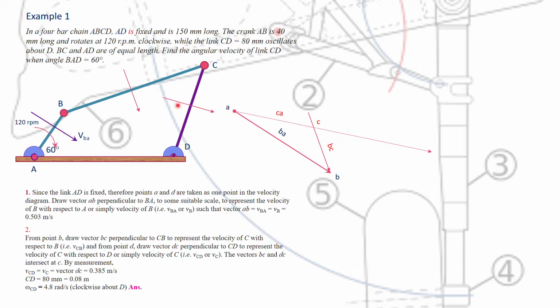Now BC, that is this. Once you have drawn it, the arrow should be pointing downwards. So you just put it downwards, and then you put B relative to C because your arrow is pointing towards B. You can put your arrow pointing towards C also, up to you, because both points are moving points. There is no fixed point, so whether it is BC or CB does not matter. But if you put BC, that means B is moving relative to C. So once you have this diagram drawn, you have found the velocity of CA and the velocity of BC.